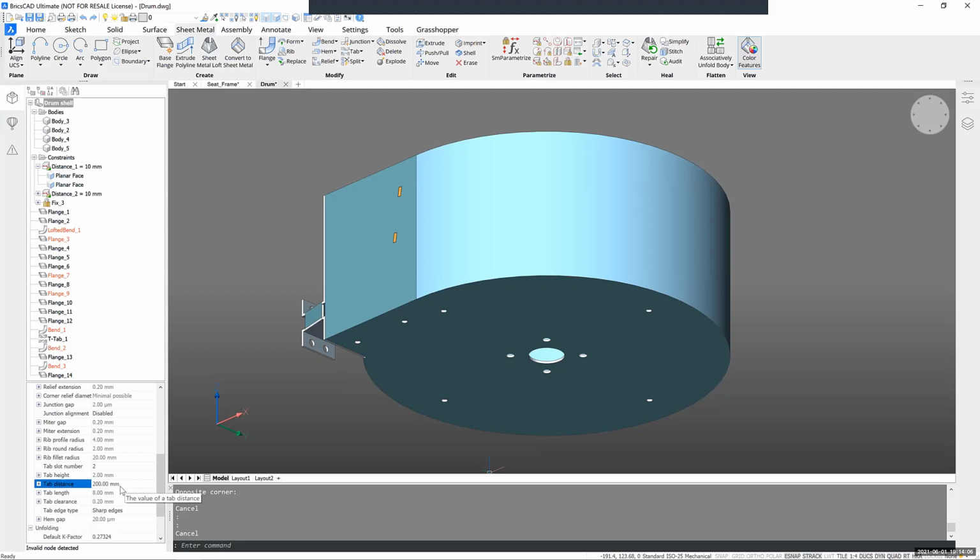You see the grayed out value, but you cannot change this right away. So either you change it to an absolute value and you can type in an absolute value, or you choose thickness ratio, and then the tabs will be placed as opposed to the thickness of the sheet metal. So we have a thickness of 2 millimeters here. And if we put the ratio on 100, it will do 100 times 2 is 200 millimeters, that the tabs will be placed from each other. So it will be spaced each time 200 millimeters. But yeah, now I will have only 2 tabs.